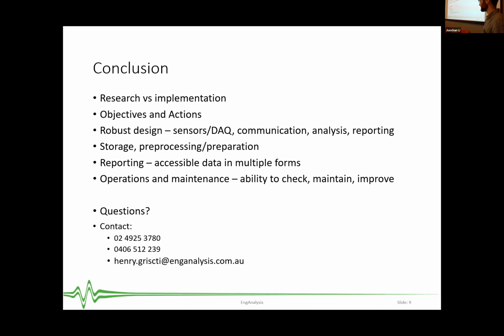So the sensor type was a tilt sensor. Because it was a heritage structure, there were a lot of constraints. You can't modify it. Everything had to be removed and the structure left in the same condition, or not touched by us or the system. So that was installed between block work. The challenge there was designing bracketry that will hold it together stably, but also be fixed to the asset, so we're measuring that and not movement of the sensor independently.